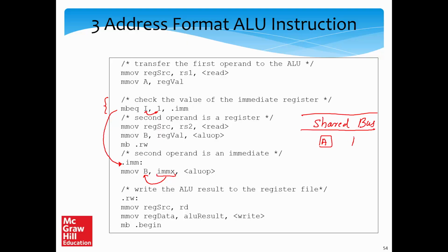So recall that the ALU is also connected to the shared bus, via the registers A and B. Then the args are also coming in, and this is the ALU. And we can optionally send this data here if it's a simultaneous thing, which is exactly what we are doing here. So we are sending MX on the bus.